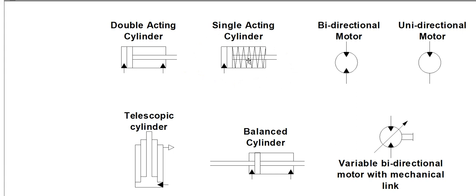Unlike the single acting cylinder. A single acting cylinder, you only put oil into one end, primarily the rod or the base end, and that will extend the cylinder. In order to retract the cylinder, you have to connect the bottom here, the base end, back to reservoir or tank, and then rely either on a spring, like this cylinder is showing, it has a spring pushing it back, or gravity. So if it would be, for an example, on a combine feeder house, those cylinders are almost all single acting and they don't have springs. We just rely on the weight of the header or the feeder house to push the cylinder back down. So it's just gravity or spring return force.